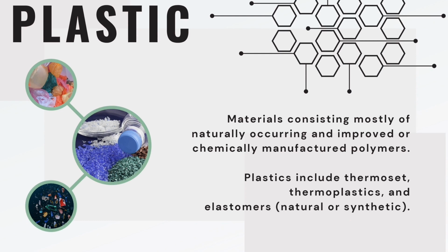Plastics are high polymer glass which can be formed into any desired shape by heat and strain. These are materials that are based on polymeric compounds, and they often contain other additives that improve their properties. Compared with most metals and ceramics, plastics have low strength, stiffness, and melting temperatures. However, they have low density and good chemical resistance.